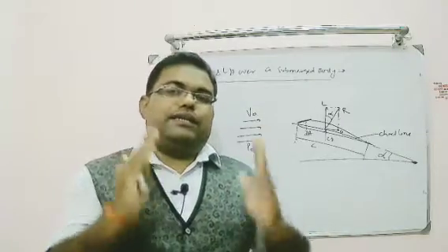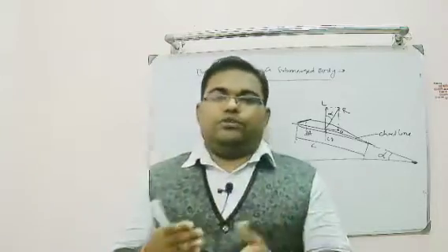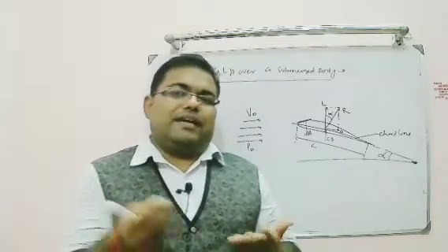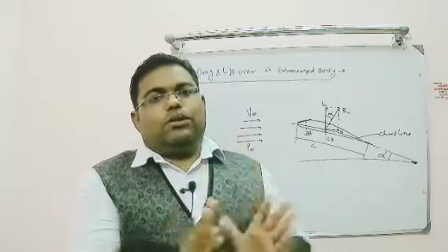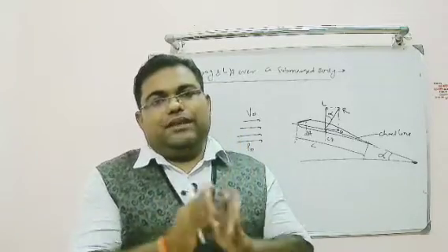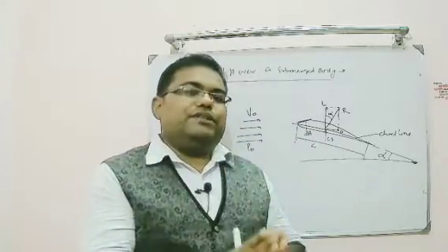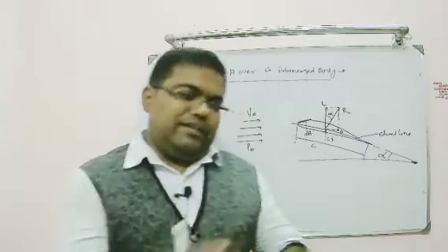Now, based on the direction of the flow, we see what the contribution of each kind of force is. If we are talking about lift, shear force will have negligible contribution, but in drag, shear force definitely will have more contribution because shear stress acts in the direction of the drag. So it will dominate particularly in the calculation of drag, but in the calculation of lift there will be negligible contribution of shear stress. Now we have to relate in what way these are related.